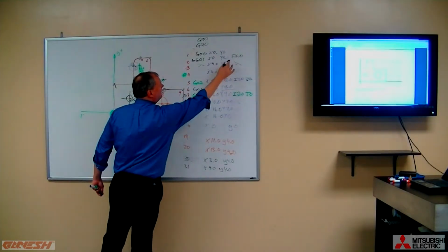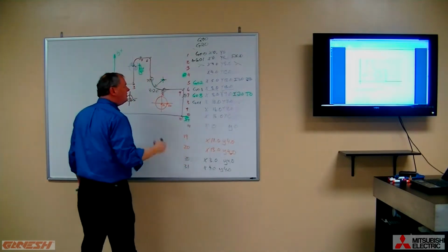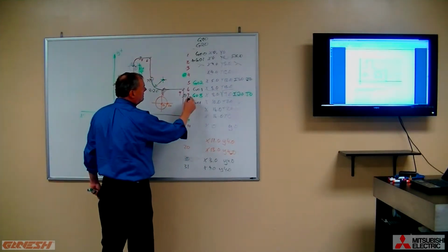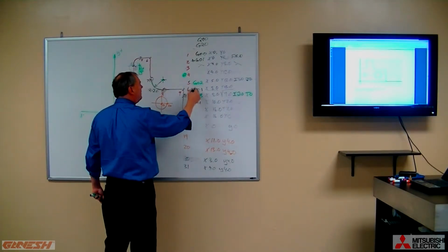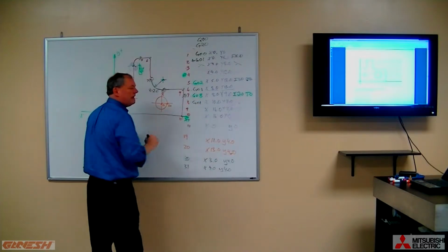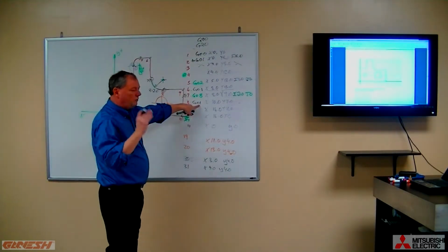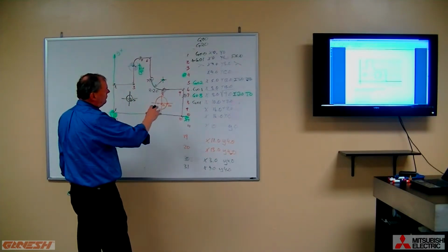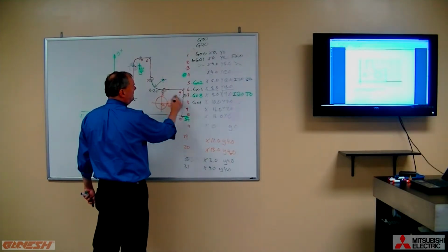Notice I haven't repeated the feed rate. The feed rate will apply for all of these blocks. So I don't even need to repeat the feed rate. All we need to do is reestablish whether we're linear or circular, counterclockwise or clockwise. We always have to reestablish that with a proper G code in the file. So now what we're doing is sitting at point number 8.